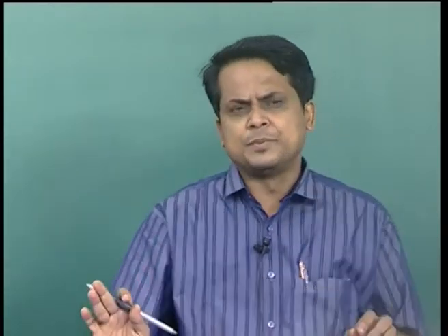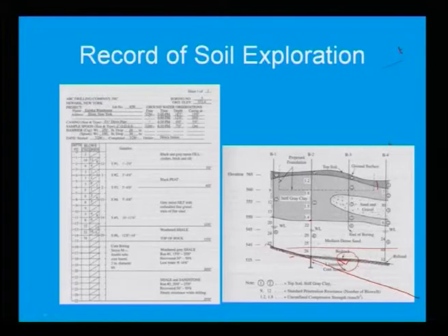Particularly this interpretation is a kind of judgment over a period of time as an engineer. If you have experience over time, your judgment will change from time to time. The more experience you have, the more refined judgment you can provide. To be on the safer side, if you have a nearby borehole like this, and if I have done only 2 boreholes, I can say the soil profile is grey clay, that is fine, so the soil profile is uniform.